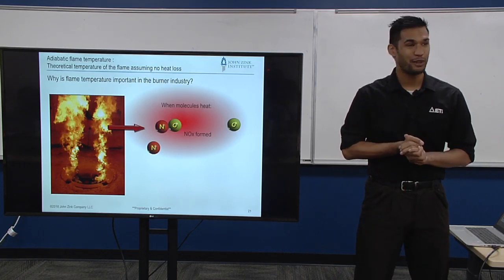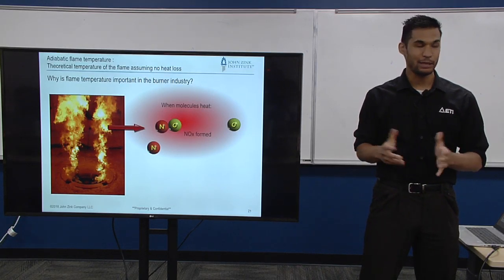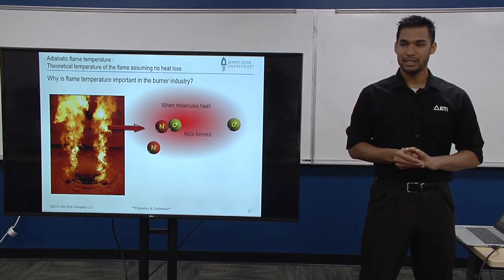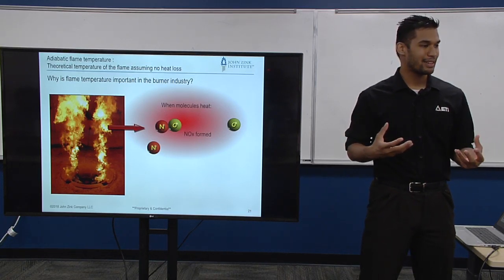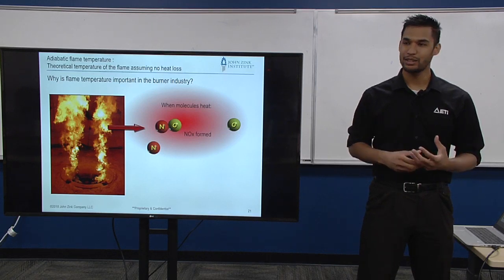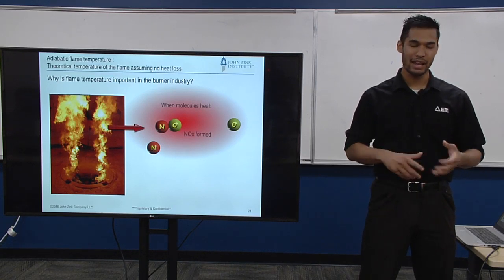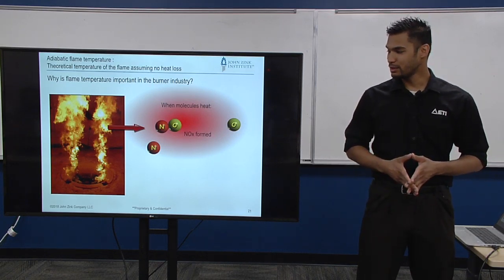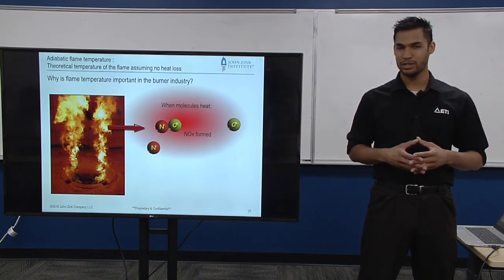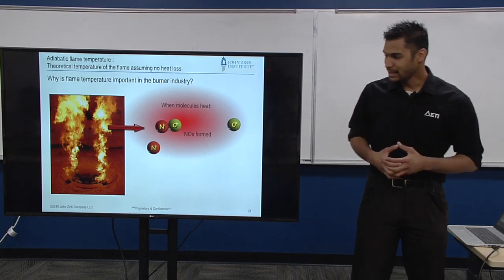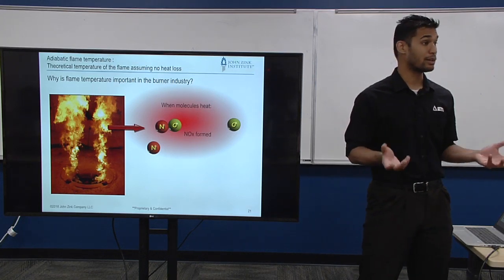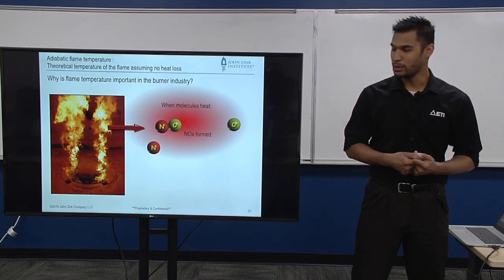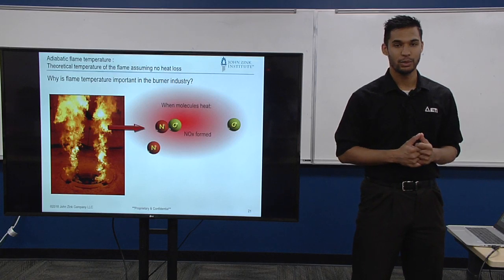When I'm running it at 3,500 degrees adiabatically, all of a sudden there's enough thermal energy in there to start causing all these weird side reactions that you would never get in a low temperature system, like room temperature, right? 3,500, 4,000 degrees Fahrenheit, that's really hot. So you can get molecules splitting apart, like nitrogen, and they can reform into pollutants that we don't want to breathe in. NO is one of them.